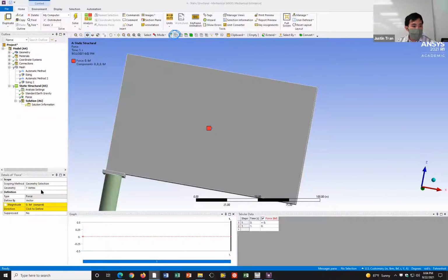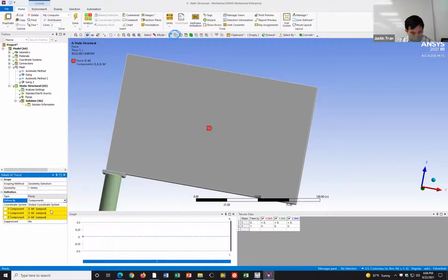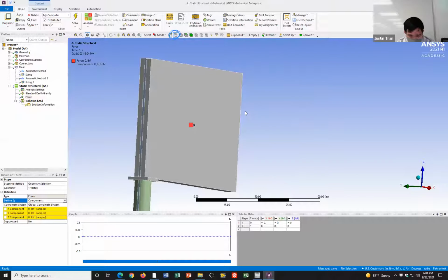Okay, so you can go ahead and apply the force there. I believe it's a force in the y direction, so the most convenient would be changing this to components and doing y. The other thing I want to walk you through before you work on the assignment is how to apply the spatially varying wind force here on the side. I believe this is implemented as a pressure.